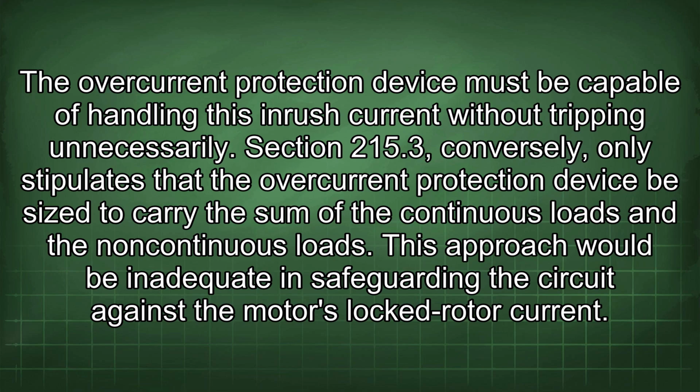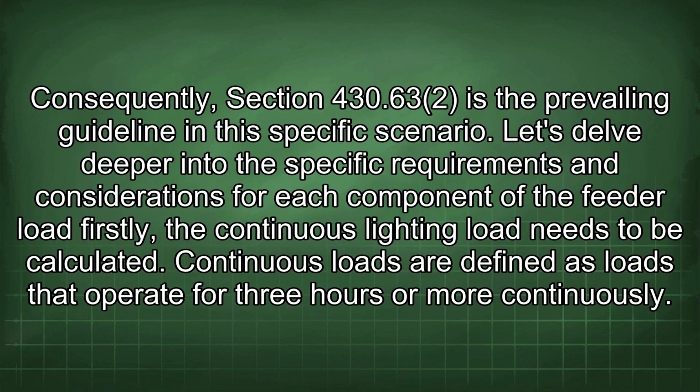Section 215.3, conversely, only stipulates that the overcurrent protection device be sized to carry the sum of the continuous loads and the non-continuous loads. This approach would be inadequate in safeguarding the circuit against the motor's locked-rotor current. Consequently, Section 430.63 is the prevailing guideline in this specific scenario. Let's delve deeper into the specific requirements and considerations for each component of the feeder load.